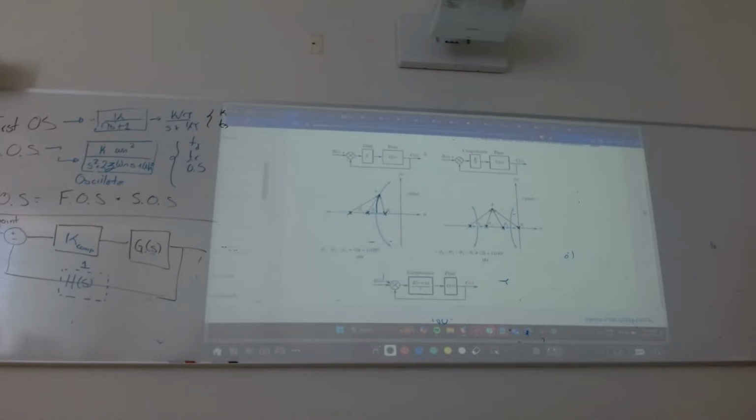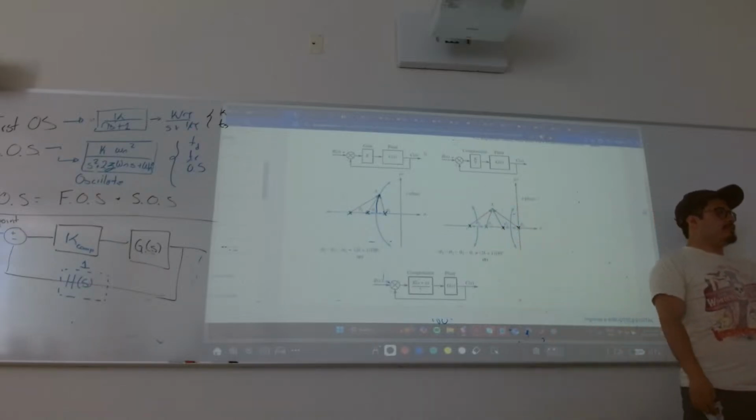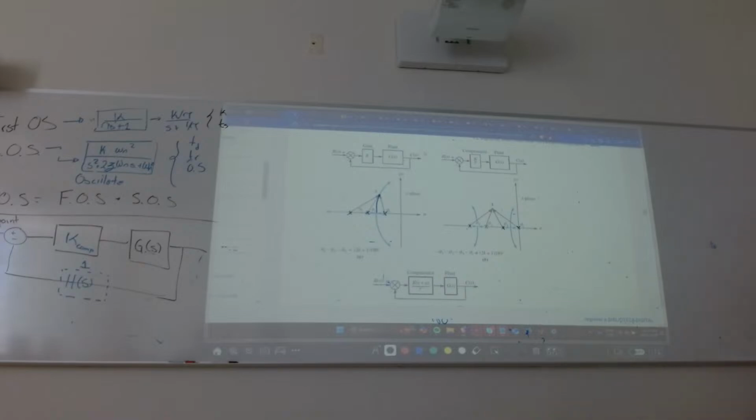Okay, I'm not being asked for the best performance. I'm just being asked, don't mess with the performance in the system. Just change the steady state error, but don't mess with the dynamics of the system. That's the requirement. That's the design requirement. And as I told you, everything depends on the design requirement. If you are being asked to make it faster, then the set of requirements is different. If you want no oscillations, then the set of requirements is different. Now the requirement is don't mess with the original dynamics.